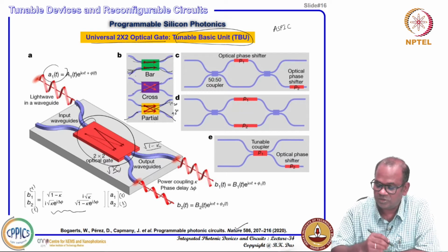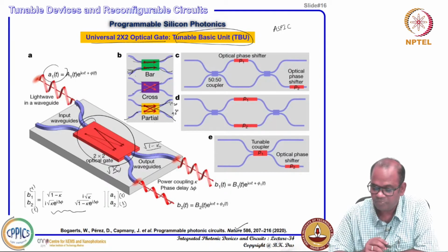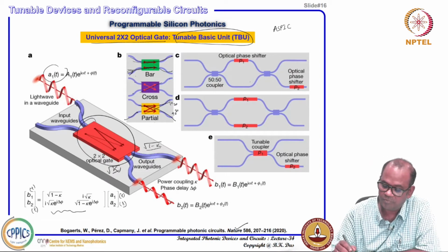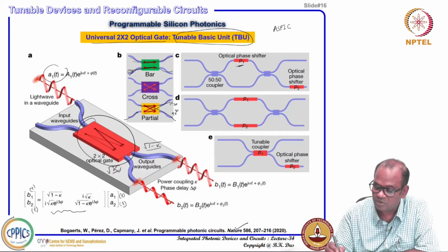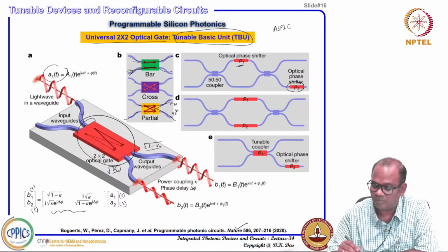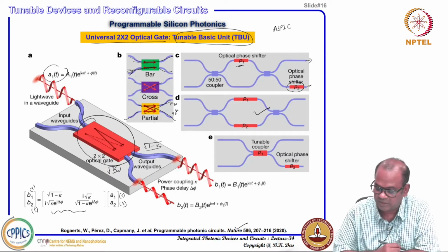So, this is a different way of phase shifter integration, shown here. Actually, you can use a simple Mach-Zehnder, with only one phase shifter here and another phase shifter, instead of on both arms, at the other arm. So, you can control phase as well as amplitude at both outputs by controlling this P1 and P2. This one I have explained in the previous slides, okay.